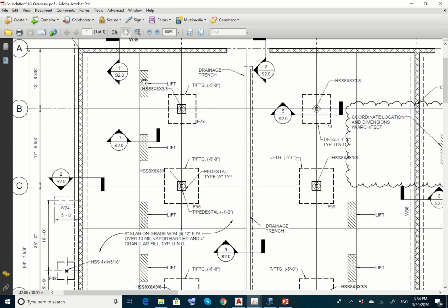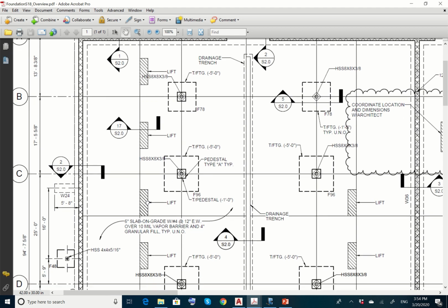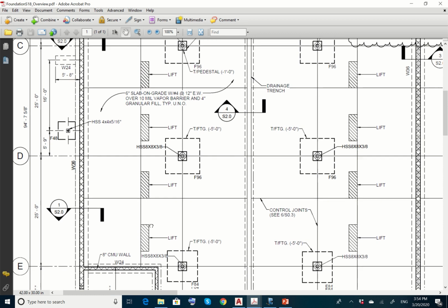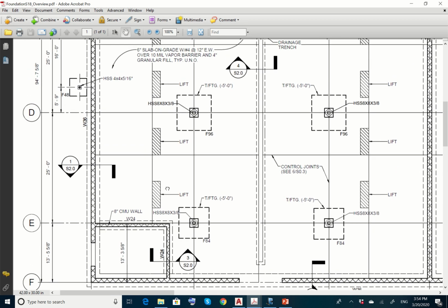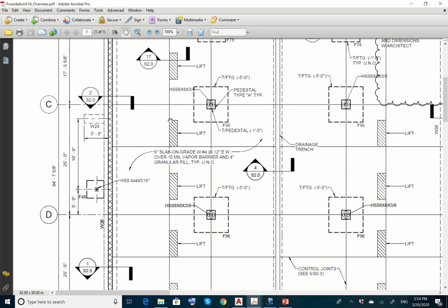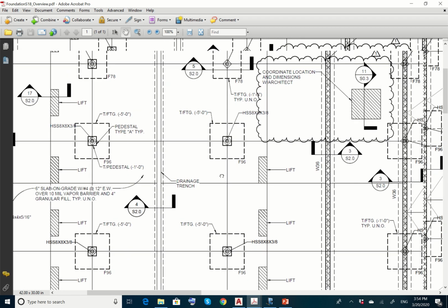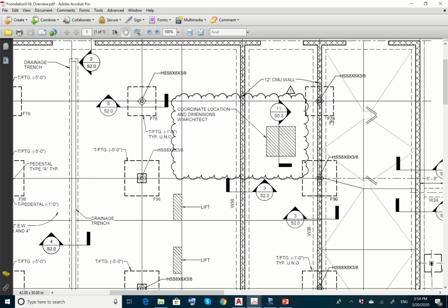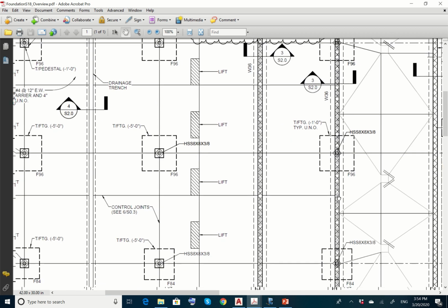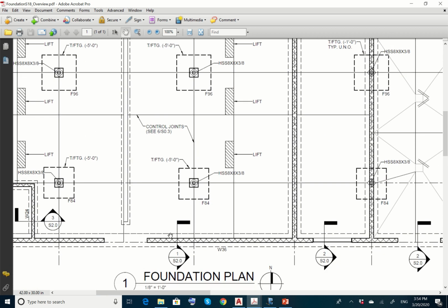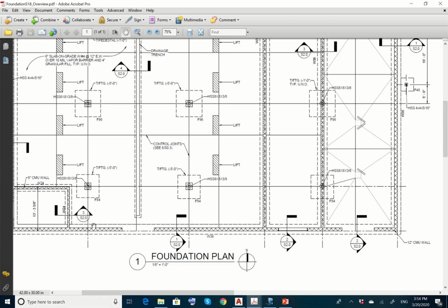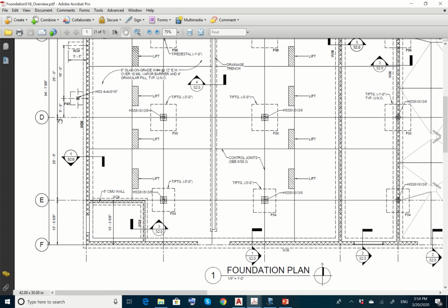There is a lift over here. How much, with the hatching? Don't forget to do those parts. How much is the dimension? It's not given, so just assume any reasonable dimensions and draw those lift parts. Over here there are those foundations, smaller and larger foundations: F78, F96. So you draw them with the dimension that is given over here. You're going to be drawing the walls, the wall foundation below it, the center lines in both directions, the columns and their foundations, and the lifts.